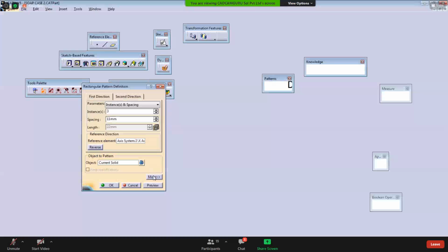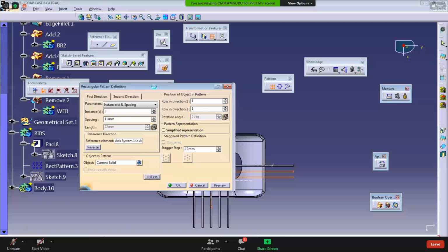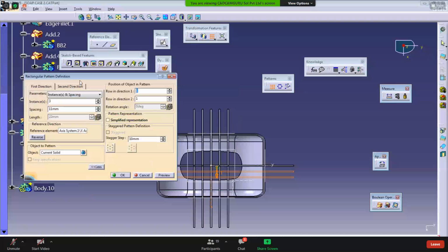What needs to be done here in this situation? You just go to the more. How do you have to define this position? What number should I enter there? Two. Yes, correct. Your first feature is counted as the second number. So this is the first feature, this is the second feature. Okay. If you enter three, then upon counting, the original feature will come at the third location. First is this, second is this, third is this. So what needs to be done here? This is 2.